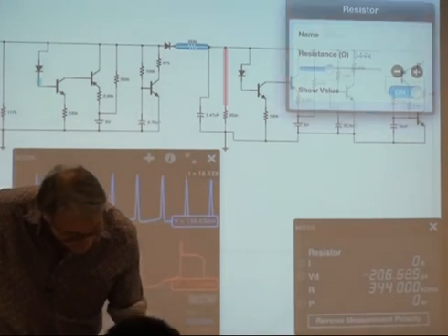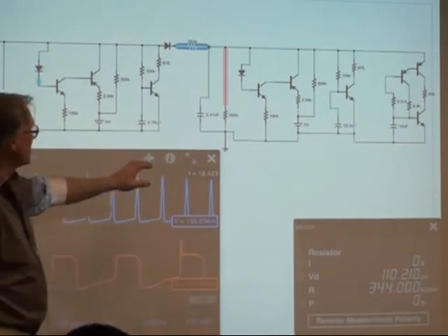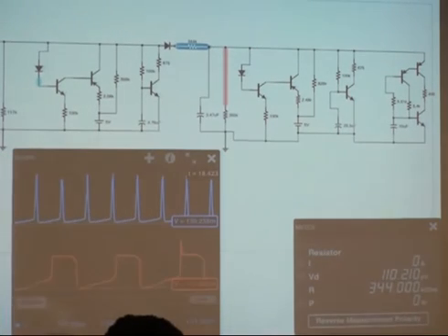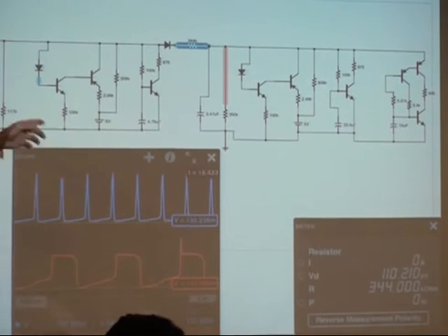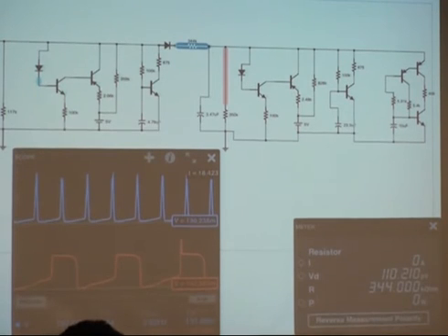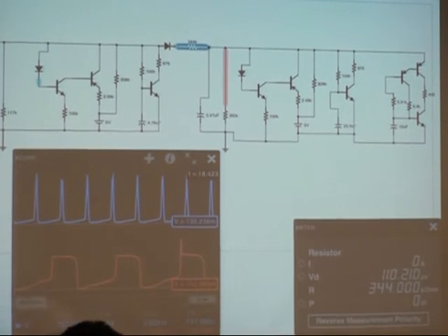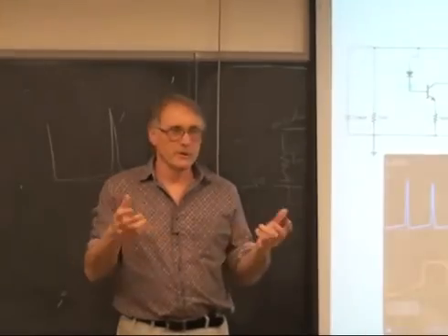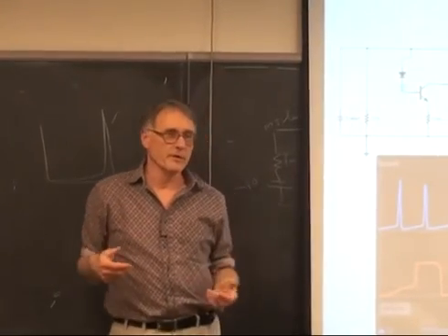One question, which I don't know the answer to, is if you build a whole bunch of these, could you simulate fibrillation? We have desynchronized firing. What I have done is to build a network of 20 or 30 of these cells, simulated a network of 20 or 30 of the cells, come up with a reasonable model for the impedance of the body, and generated a pretty good looking ECG by doing a linear weighting, linear addition of the various pieces.